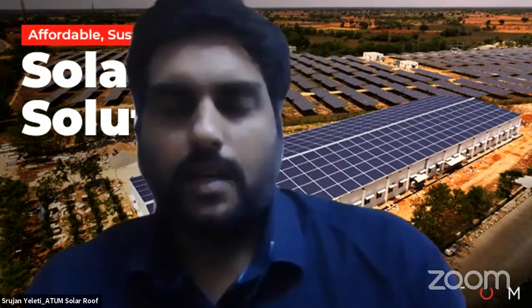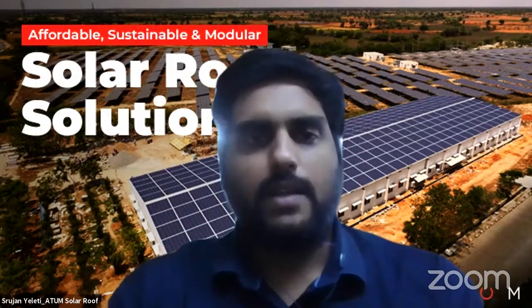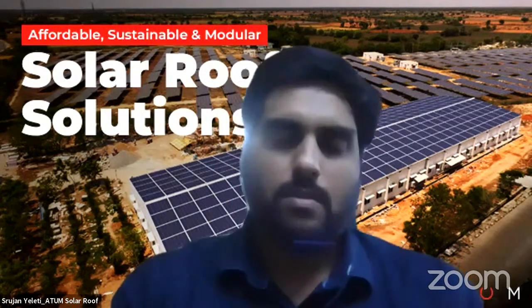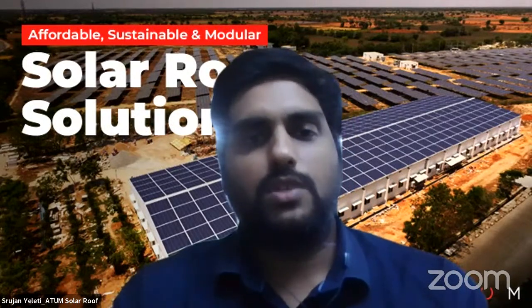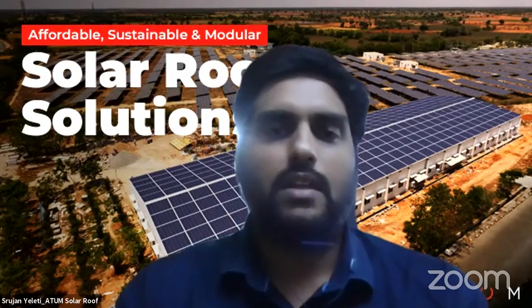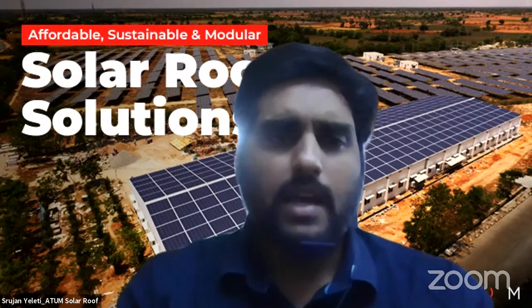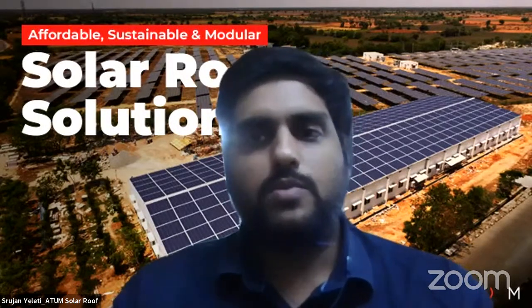Yeah, thank you, Mr. Anand. In terms of deterioration in power generation, it is the same as the normal solar panels. There is about a 0.7 to 1% deterioration every year. And the warranties that any solar panel gives, that's exactly what we are giving, also mandated by the ministry, that at the end of the 25th year, you have a minimum of 80% generation from the solar panels. It's not exactly linear, but not even too non-linear, so it's somewhere between that. But still, in 25 years, you will end up having 80% generation at the end of the 25th year. Every year, there will be about 0.7 to 1% deterioration in the generation.